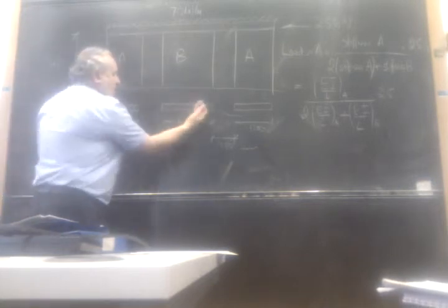So quite a lot of people probably in doing this problem would have stuck L in as that. But if you think about it, we've got this cross section here resisting the bending. So the L's the same for them all.